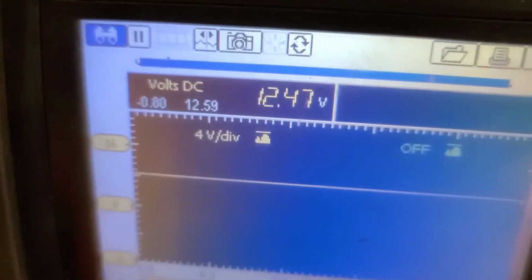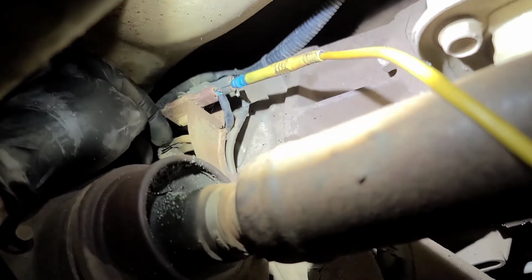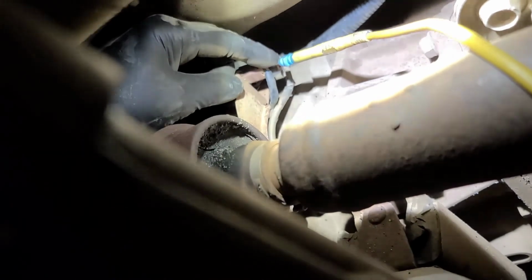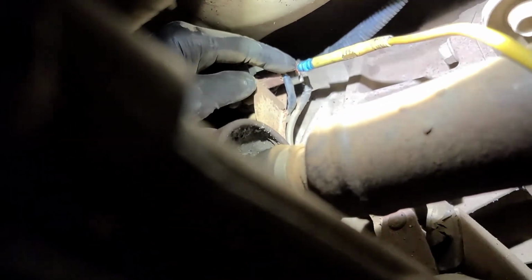and as you can see, it doesn't change state, but the transfer case is switching, so I think this switch is defective. And if it doesn't indicate that the shift took place, then the transfer case control module won't energize the front axle to lock up the front axle. If I manually lock it up with the scan tool, the four-wheel drive works, so I'm leaning towards this switch. I wonder what would happen if I ground this wire. That should simulate what the switch does when it's in 4 high. I'm going to try grounding that wire.